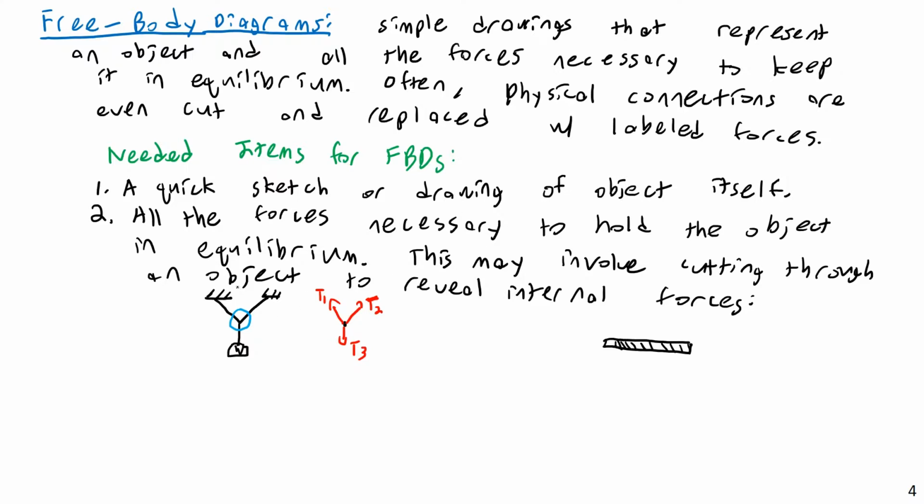So that's kind of how I perceive free body diagrams. I know that's kind of weird, but the way I perceive them is, if I had this magic wand that could arbitrarily apply forces of any magnitude and in any direction I wanted, if I could snap my fingers and create a force out of nothing, what would I have to do to keep an object at the location it currently is? In other words, that little particle here, if I had this magic wand, what would I have to do with it if I literally cut it out?